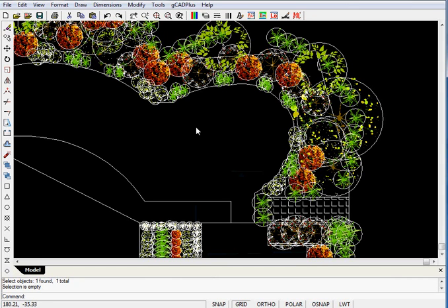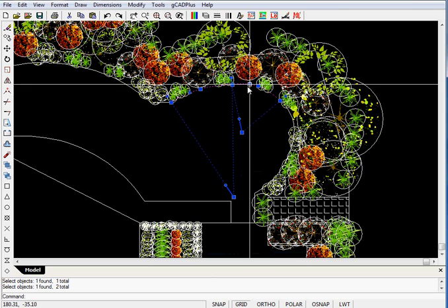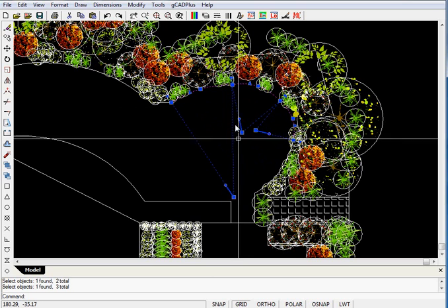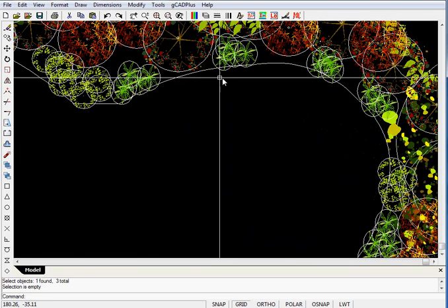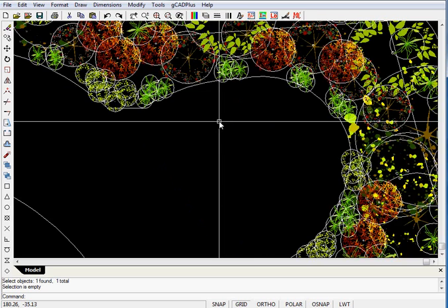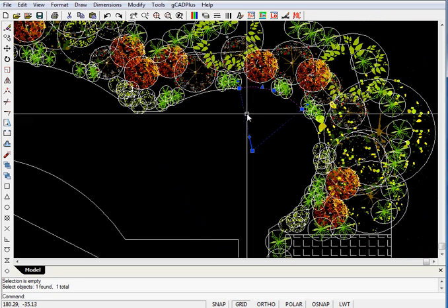You may be able to see that as I click on this complex shape through here, it consists of a number of arcs that are joined to one another. The center point of those arcs is somewhat scattered, and if I escape from there, if you look at the shape along here, it's not perhaps as smooth as we would like. And you might want to use a polyline to define this area through here.